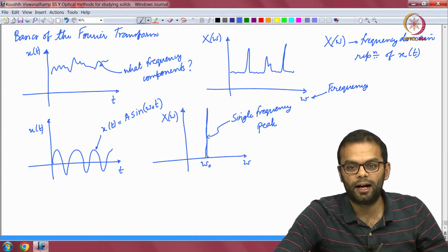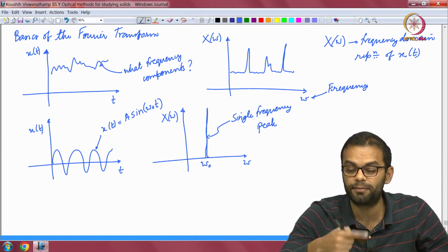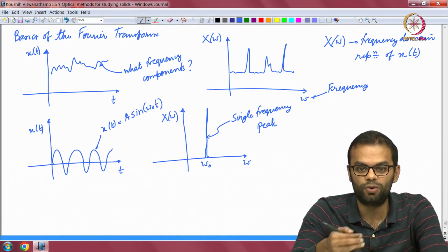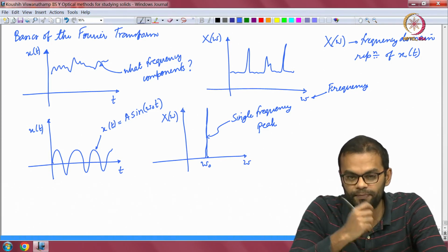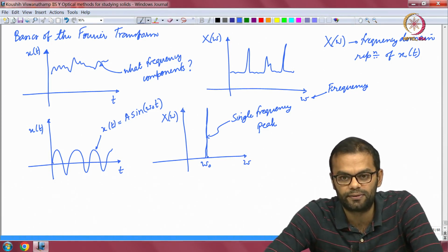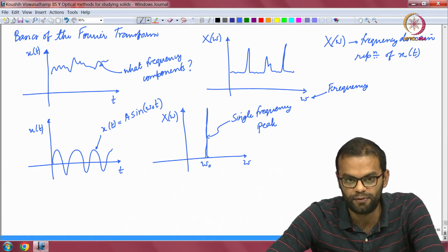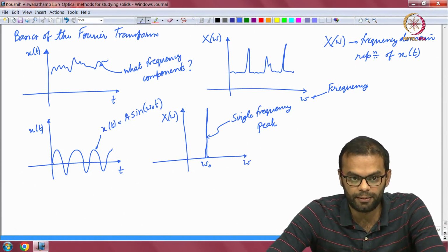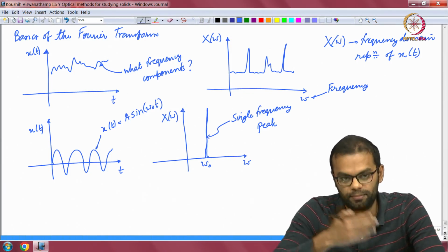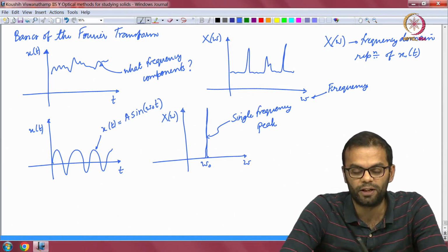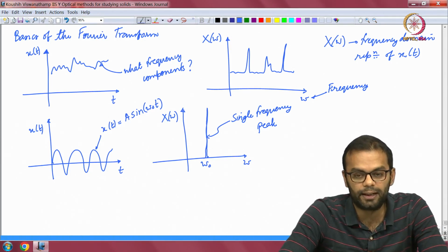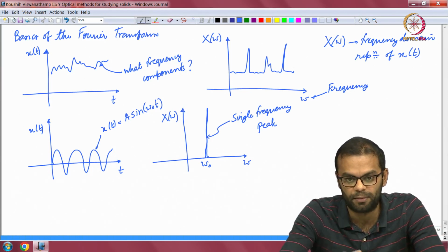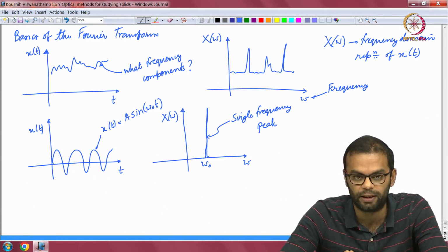So the Fourier transform basically is giving you the frequency information that is contained in the signal, and this type of information becomes very useful. One of the reasons it is very useful is because it allows you to evaluate what are called convolutions. Again, we discussed this in the context of digital image correlation, but I will briefly mention it again, where convolutions are basically integrals along t, whatever t is, it could be a spatial variable also, and the corresponding representation in the Fourier space becomes a multiplication, just a product, right. So it is easier to evaluate.